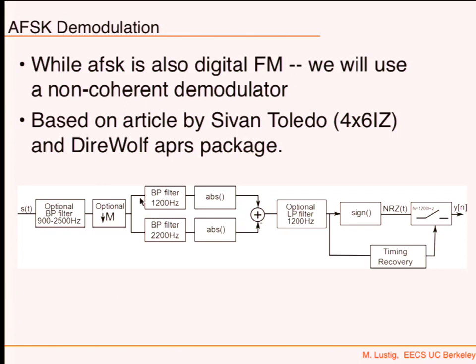And then that will give me my y of n, which will be a binary signal of 0 and 1. I can convert this plus minus 1 into bits again. Okay? So that's the modem. Now, what we didn't have last year, and we have this year, is another part which does timing recovery.